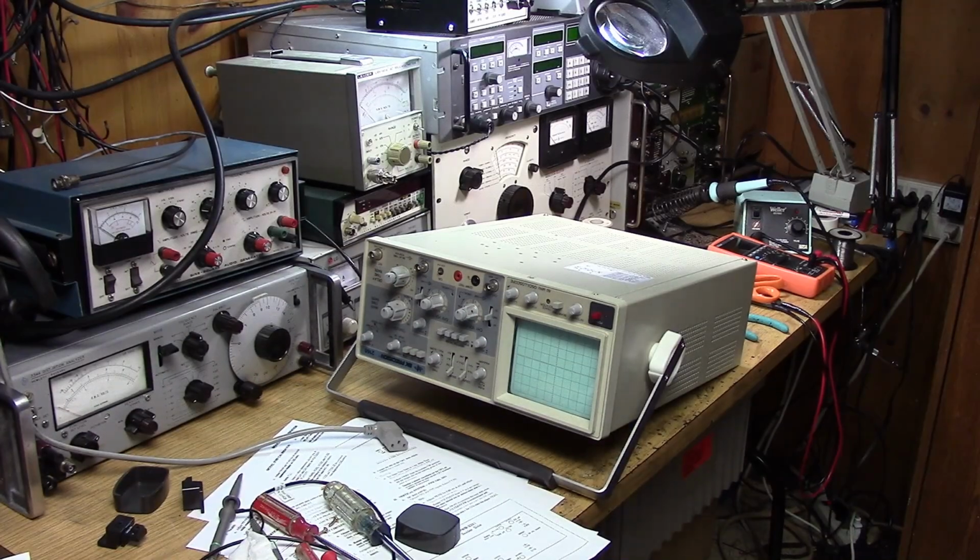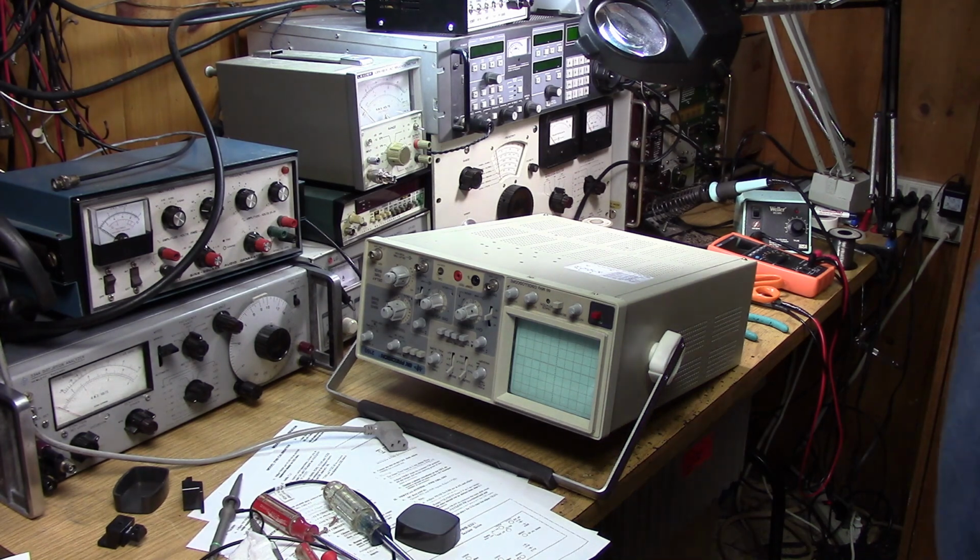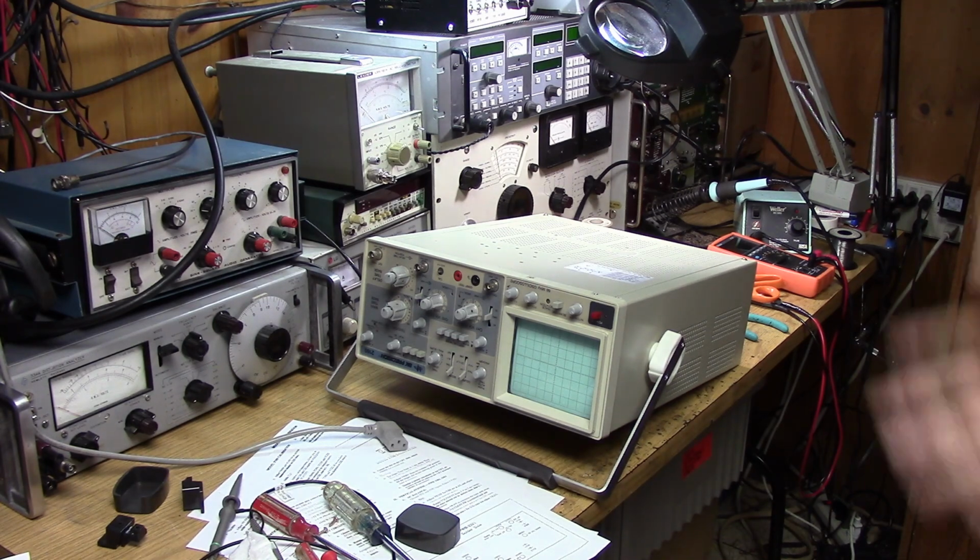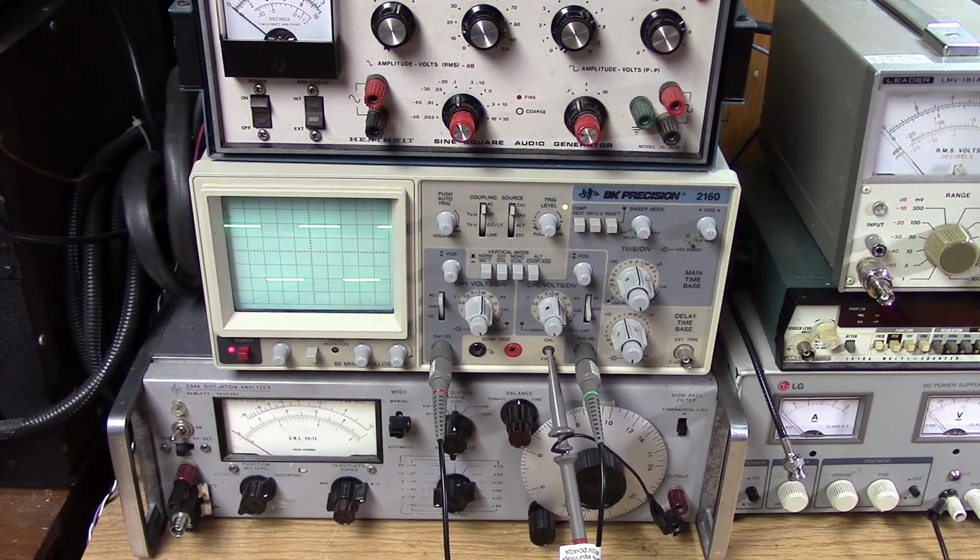So I finally got sick of that oscilloscope, and the thing just wouldn't focus. So I did have to take it all apart, and I finally found the astigmatism potentiometer. And I thought while I was at it, I might as well go through a whole calibration on the scope. I'm not going to bore you guys with that, but even a poor old analog scope like this BK deserves to have a calibration now and then. And when do we fix these things? When they finally drive us completely nuts and we throw it in the trash, or we dig into the manual and see if we can fix it or calibrate it.